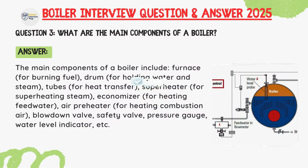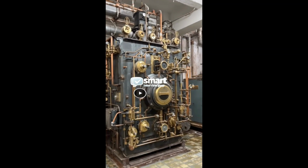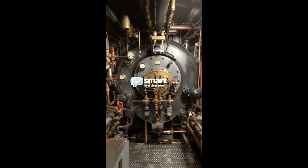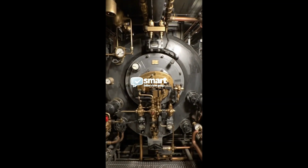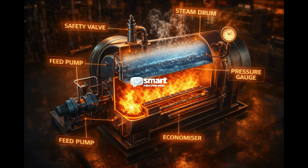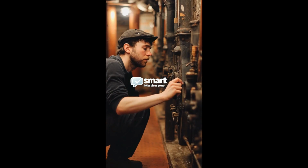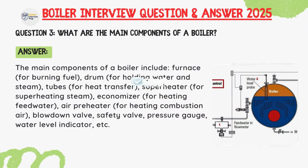Question: what are the main components of a boiler? Answer: the main components of a boiler include furnace for burning fuel, drum for holding water and steam, tube for heat transfer, superheater for superheating steam, economizer for heating feed water, air preheater for heating combustion air, blowdown valve, safety valve, pressure gauge, water level indicator, etc.